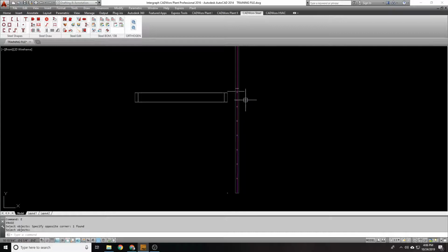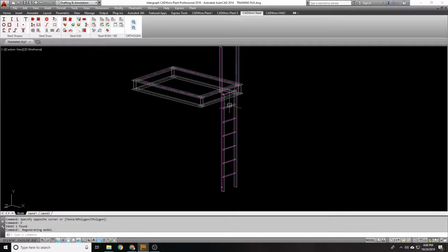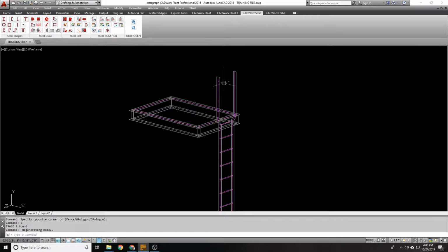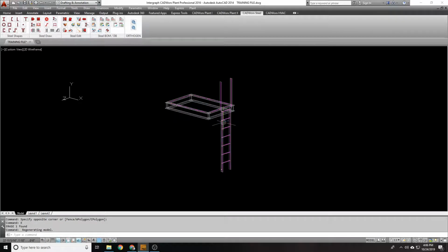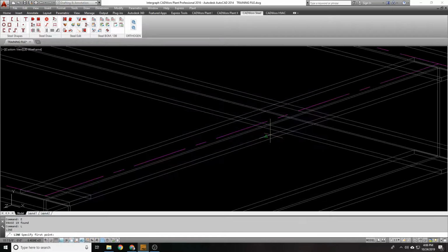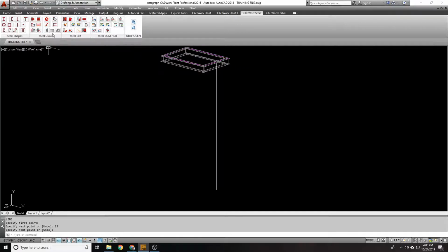All right, now let's put a cage. Now, the thing is, this particular ladder is not tall enough to put a cage. We only did a 7-foot ladder, and our minimum clearance is 7 feet, 7'6" in this case. You do have this extension beyond that you could technically put a cage on. I've seen some really stubby cages in situations like this, but let's just make it easier on ourselves and draw a line that's down 15 feet. So we have a legitimate need for a cage and room for one.